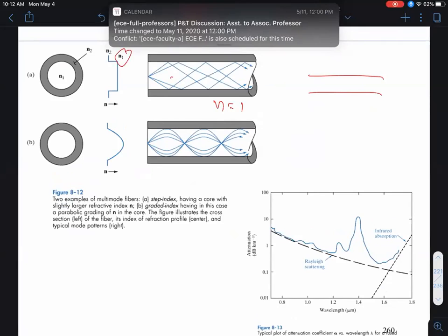It looks like hair exposed to the air, because then any surface roughness can cause the light to be scattered out. In fact, if you look at these cheap optical fibers in toys and you shine light at one end, you can actually see some light through the optical fiber, and that's bad, right? That means that the light is actually scattering out. So to prevent that, you cover the core of the optical fiber with what's called a cladding layer. But the cladding layer has a refractive index lower than in the core, but still higher than in air, okay? What that does is it restricts the light within the fiber itself, and you don't reach the air-fiber interface where I'm susceptible to light leaking out, okay?